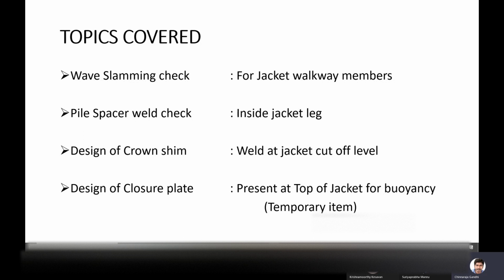But if there is any wave slam on the region at the top of the bottom of steel, if it comes in an unavoidable situation, yes, we have to perform wave slam for that deck elevation also. That may be applicable for old platforms, where it was not considered in those days, so we have to check for that when it comes to brownfield. But in most cases nowadays, we calculate everything for the air gap, so the members exposed to the wave slamming check are only the jacket members.